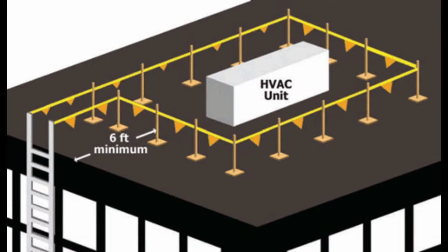When erecting precast concrete members, the control line shall be erected not less than 6 feet, 1.8 meters, nor more than 60 feet, 18 meters, or half the length of the member being erected, whichever is less, from the leading edge. The control line shall extend the entire length of the unprotected or leading edge and shall be approximately parallel to the unprotected or leading edge. The control line shall be connected on each side to a guardrail system or wall.